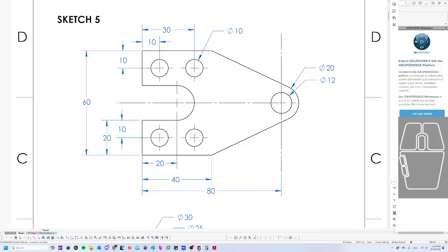So let's do a center point arc. And again, since it's 90 degrees between the other center point and the start of this leg, I'm just going to put my center point of this inside arc at the intersection of those two dotted lines to line it up, just save me some work in the future.